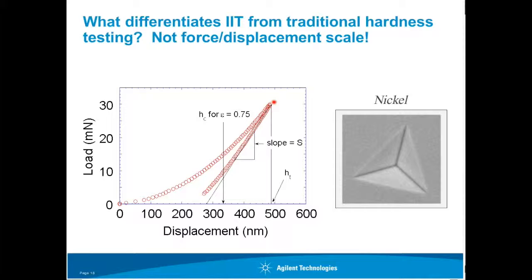The first major benefit is that, from this force displacement information, you can actually calculate the contact area, and you can do a pretty good job of it. That's called the Oliver-Pharr model. The major benefit is that in a lot of practical circumstances you don't have to go and measure the contact area microscopically.